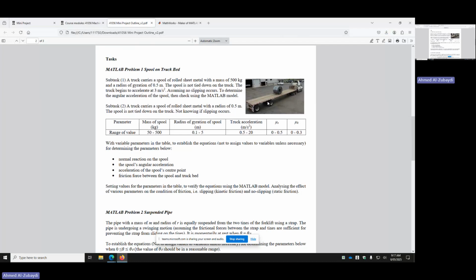So most of the machinery is going to have something like a pedal. You press it and you make it work. When you remove your foot from this pedal, it will stop immediately. It's not only cutting the power and letting it move for a while, but it's also going to be braked, because we have this clutch brake system.